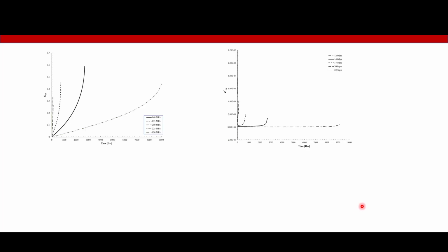Okay. So now we try to slowly go in the direction of creep deformation, and I'll just discuss a common mistake which people, usually students, make. This is a plot of creep strain versus time at different values of stress. Although the values might be very small, the time goes from 0 to 9,000 hours and the strain goes from 0 to 0.7. It's not in percentage, it's an absolute value, and the stress increases as you go up the curve.